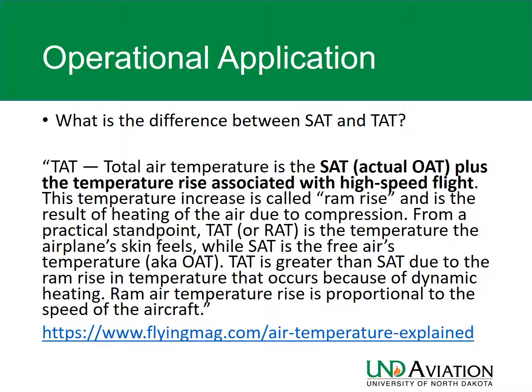It's from flyingmag.com. TAT, which is total air temperature, is measured by one or more probes that we have installed on transport category aircraft. Total air temperature is SAT plus the temperature rise associated with high-speed flight. That temperature increase is called ram rise, a result of heating of the air due to compression.